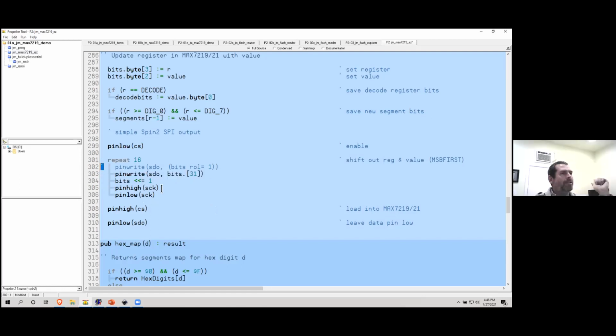All right. Yes, John. I think what could be pointed out is that the pin write, because you're only talking about one pin, SDO, it's only going to look at the LSB of the second term. Yes. That's why that works. This is defining one pin. In fact, I have parentheses here. I may have actually had this at one time and then realized I didn't need it, masking off everything except the LSB. But since SDO is defined as one pin, it's only going to write the LSB of whatever the value is in this field.